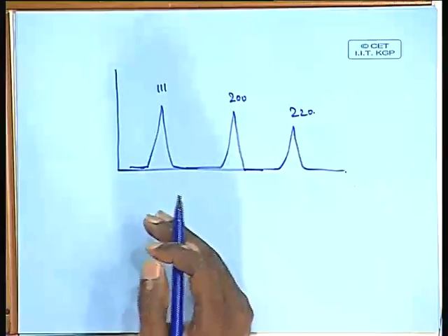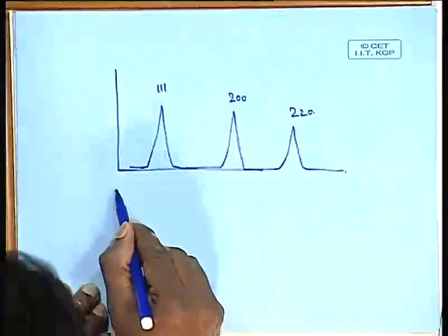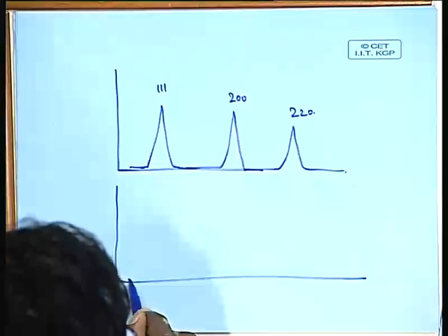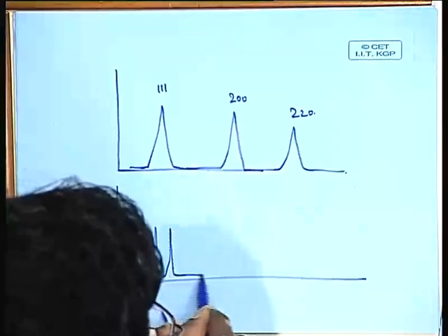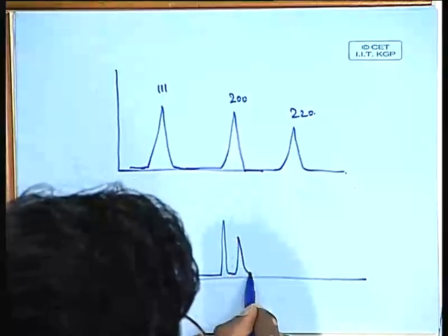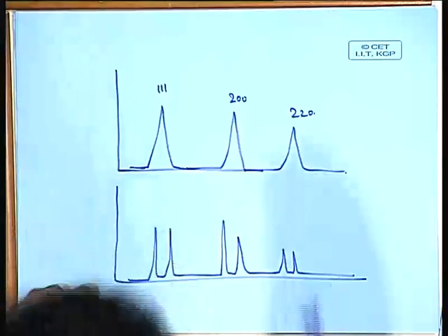But if this was conventionally solidified under slow cooling conditions, what will you get? You get two peaks. For each peak you will get two peaks, one corresponding to the silver, another corresponding to the copper, because you have silver solid solution and copper solid solution. That is what a eutectic mixture is. It is alpha plus beta, we say. In this particular case, alpha and beta both have the same crystal structure, and obviously their peaks will be the same, because both are FCC, you will have FCC peaks of both.